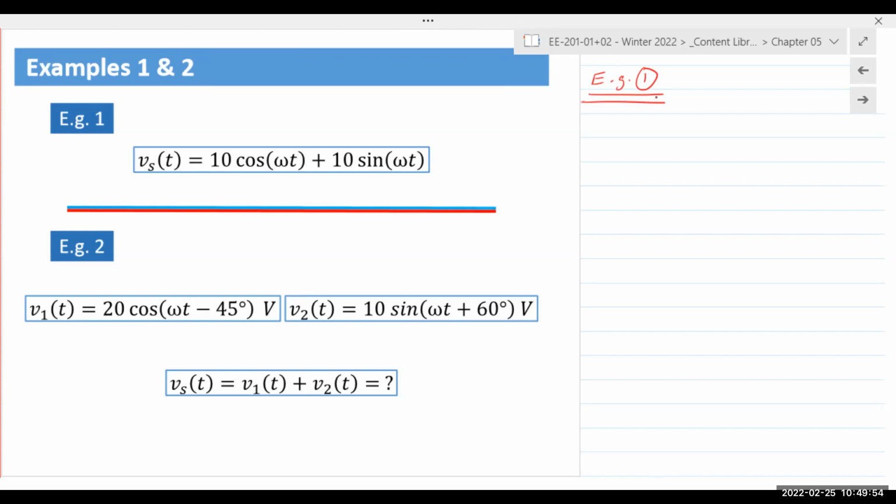So when you take the incoming signal, you invert the phase and you add it to the same signal, it cancels out. Vector quantity, minus 180 or plus 180 cancels it out. Okay. But if the frequencies are not the same, all you're going to get is like jangling noise.